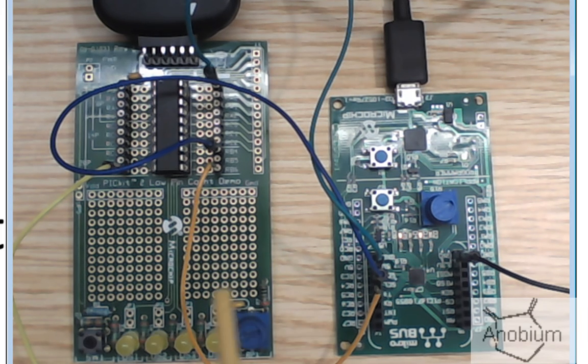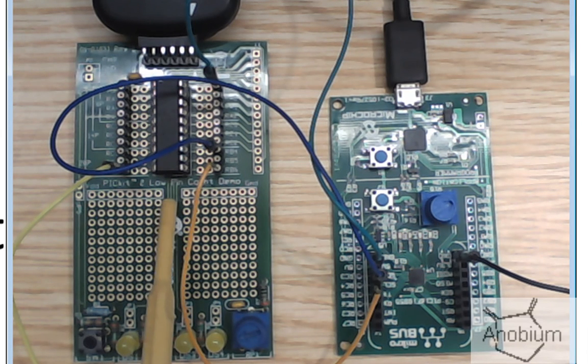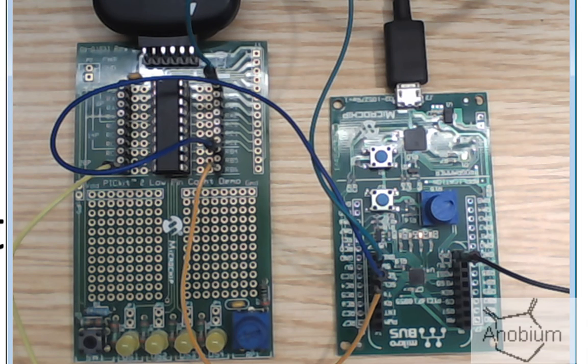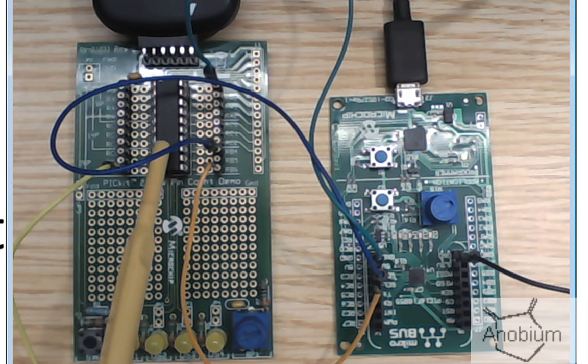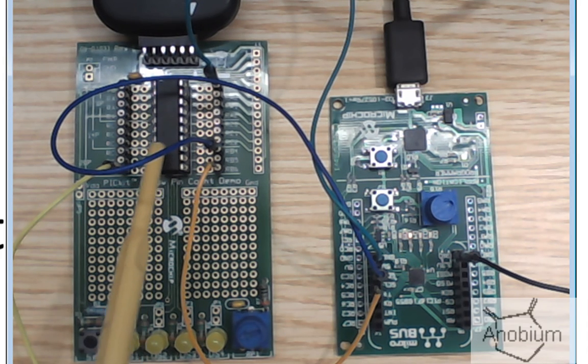I can have 128 devices hanging off of what's called a master. That's using 7 bits. You can have more, but we just don't support the 10-bit addressing. So we're not going to go into I2C in any great depth. There are lots of resources up on the web that you can have a look at. What we've created is a master in this 16F690, and this is a slave.